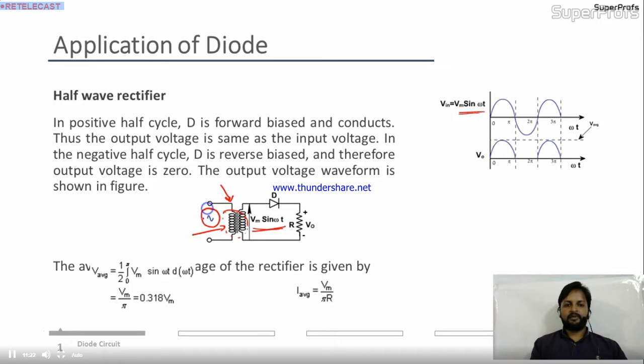We'll apply the input over here and we'll get the output over here by linking of the flux between these two coils. Remember, we have seen in the circuit theory mutual inductance. Because of this phenomenon, the voltage of the primary will be linked with the secondary. Why are we using this? Because we can improve the quality, meaning we can step it up or step down, based on our requirement.